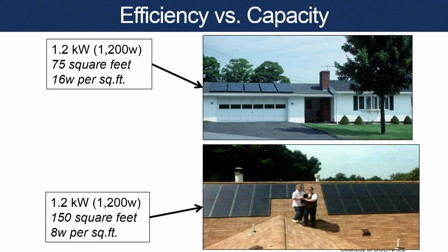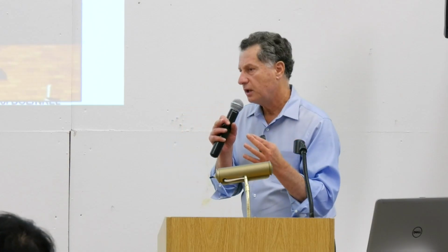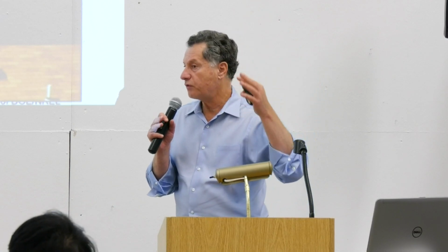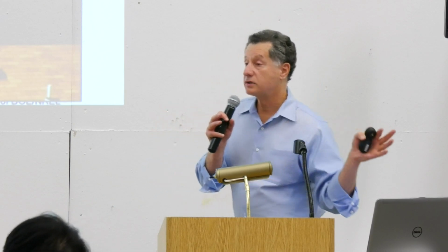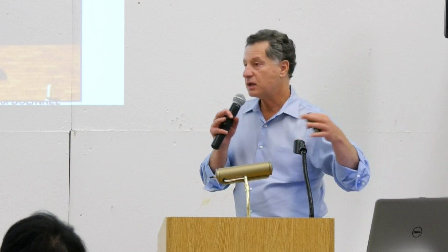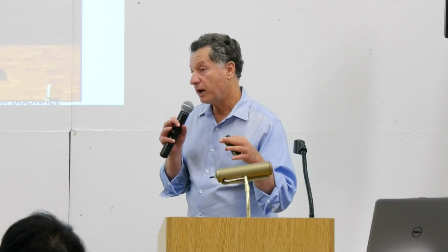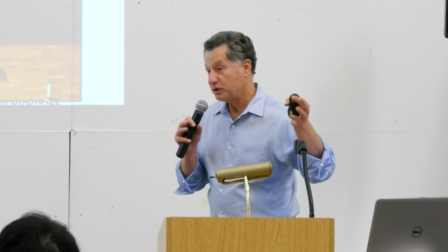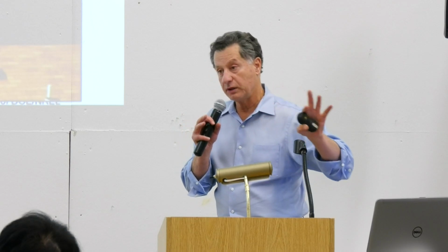Now, the more efficient solar panels are, the more they'll cost. Right now on the market, the efficiencies range from about 16% to about 22%. So it's not an order of magnitude. There's some increase in it. You may pay more for that. But if you have a big warehouse, let's say, like Bill said, and you can easily cover your ZNE load, you can buy lower efficiency panels for a better price. They'll have the same capacity and the same warranty, and you'll get a good deal. You can actually lower your price and get a really good deal.